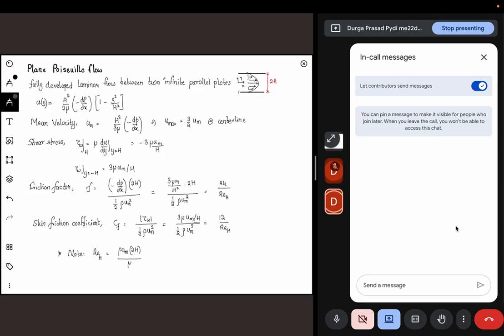And then skin friction coefficient, this is again with respect to the shear stress. If you want to find the shear stress, you need to first calculate the Reynolds number, calculate the skin friction coefficient, and multiply with this. If you're interested in finding the pressure gradient term, then you have to use the friction factor. You can see here that friction factor is 2 times Cf. So if you use the wrong coefficient, then you'll be off by more than 100%. Is that clear?